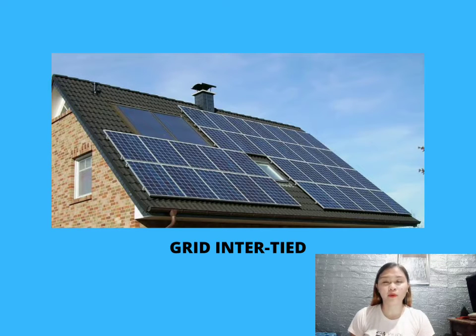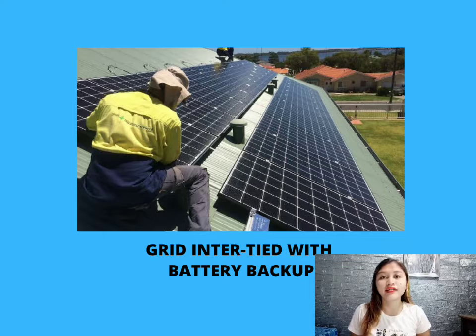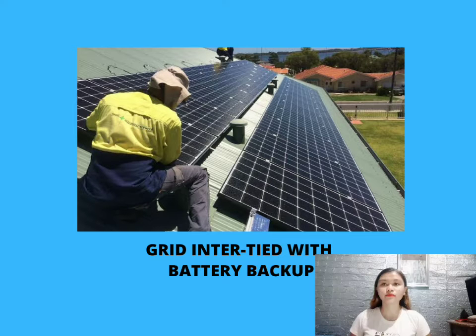The grid-tied solar power system is the common one. A grid-tied or grid-connected solar power system is connected from the home to the traditional electricity utility grid. This power system does not include any storage battery. The grid-tied system with battery backup, also known as a hybrid solar system, is also connected to the traditional utility power grid and adds battery backup to the system. The addition of the battery backup enables the system to balance production and demand and protects against power outages.